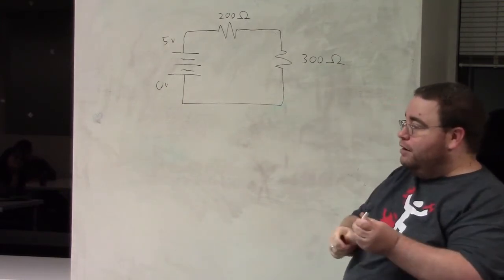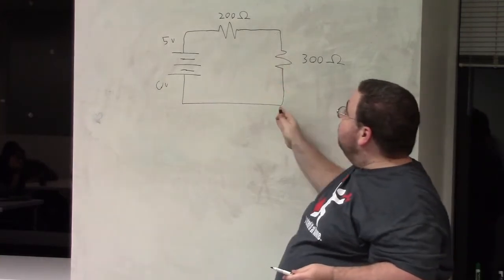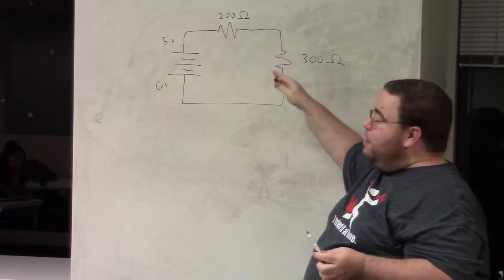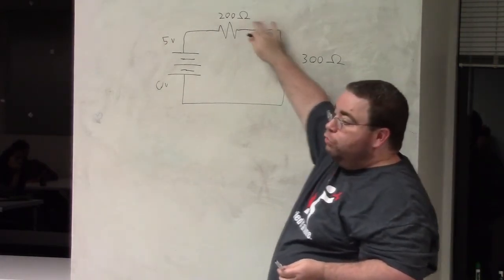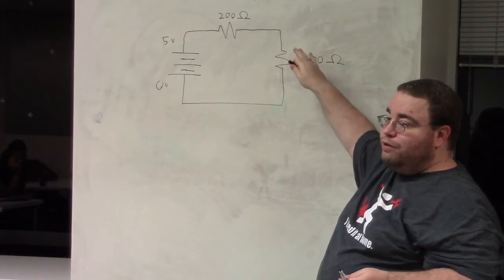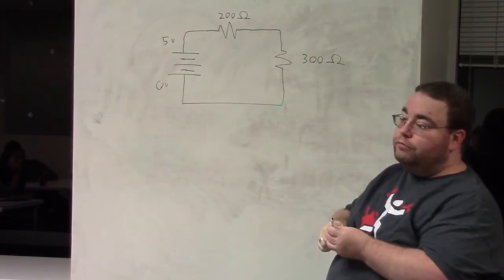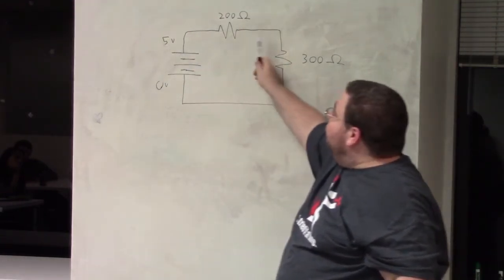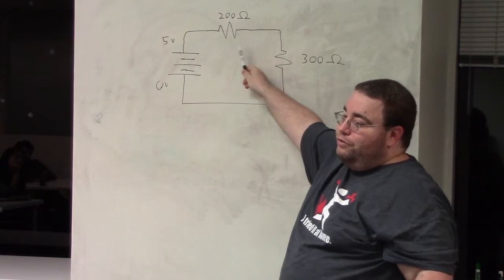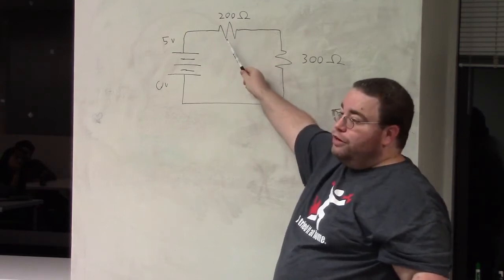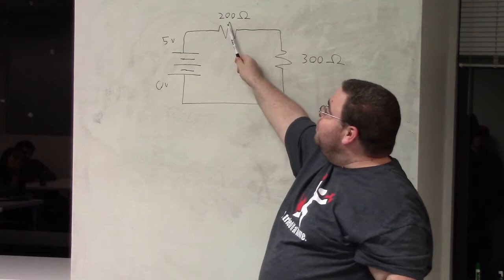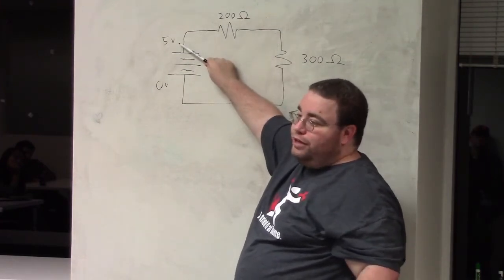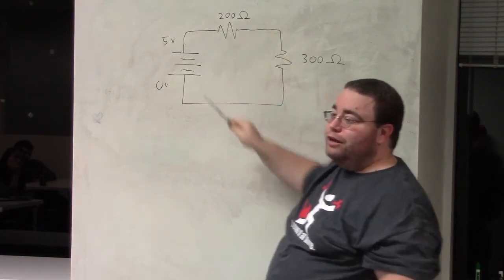It turns out that you can just figure out, based on whatever proportion this resistance is to the total resistance, what the voltage drop for that resistor is. Note that if this were 10, not 5, the voltage here would be 6, not 3. There's nothing magical about the fact that this is a 200 ohm resistor. It's just the relationship between this resistance to this point and the total voltage. Because again, Ohm's law. These things are all related.